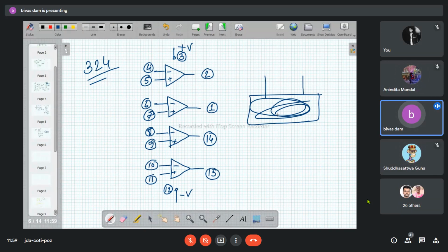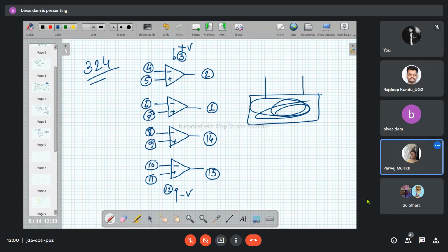So what is the requirement of the slew rate? Infinite, plus minus infinity. But do operational amplifiers have infinite slew rate? No, sir. They have slew rates of the order of volts per microsecond, maybe 10 volts per microsecond, maybe 50 volts per microsecond. That is the standard slew rate value.